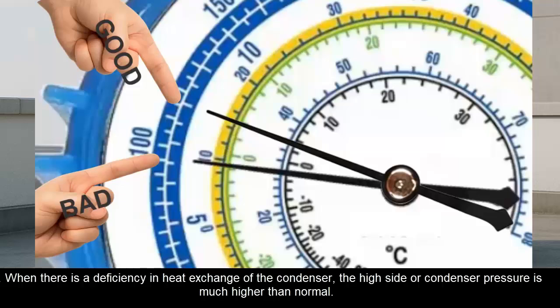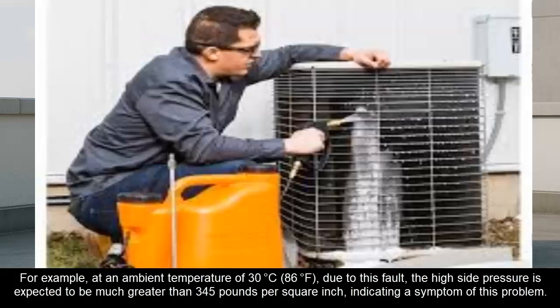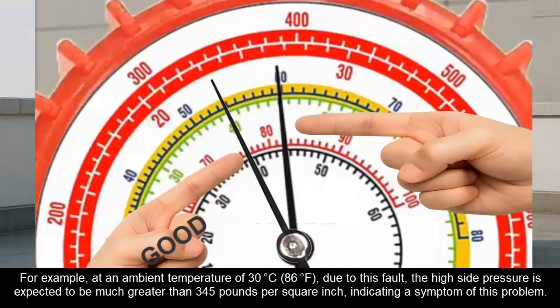B. When there is a deficiency in heat exchange of the condenser, the high side or condenser pressure is much higher than normal. For example, at an ambient temperature of 30 degrees Celsius, 86 degrees Fahrenheit, due to this fault, the high side pressure is expected to be much greater than 345 pounds per square inch, indicating a symptom of this problem.